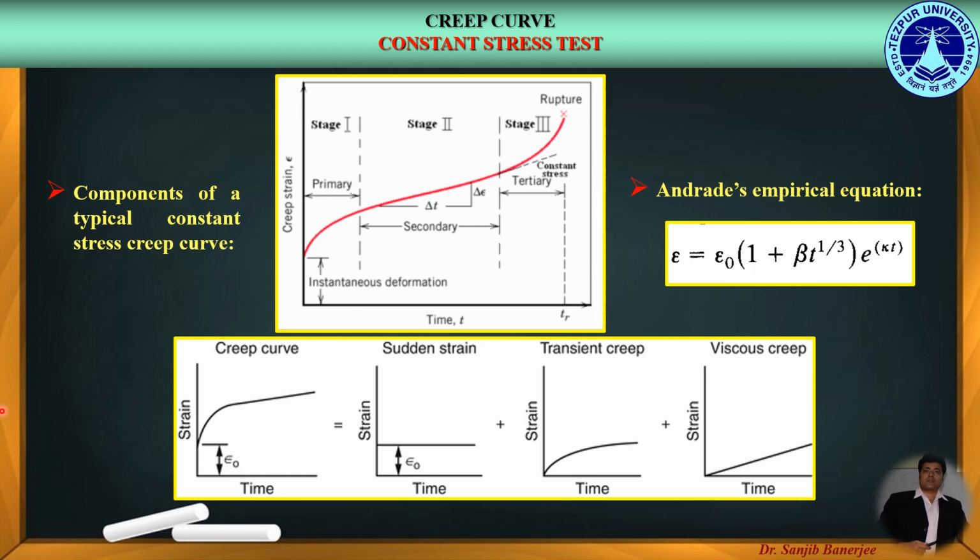When constant stress tests are made, it is found that the onset of stage 3 is greatly delayed, as indicated by the dotted line in this figure. In engineering situations, it is usually the load but not the stress that is maintained constant. So, a constant load creep curve is more important. However, fundamental studies of the mechanism of creep should be carried out under constant stress conditions.